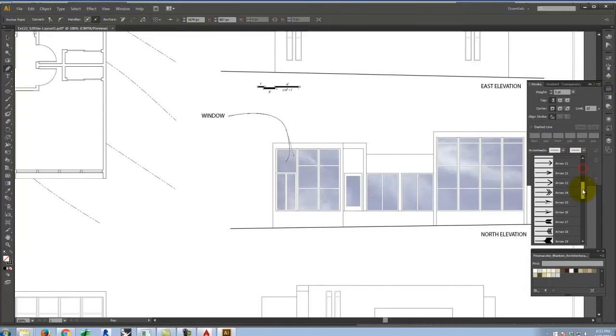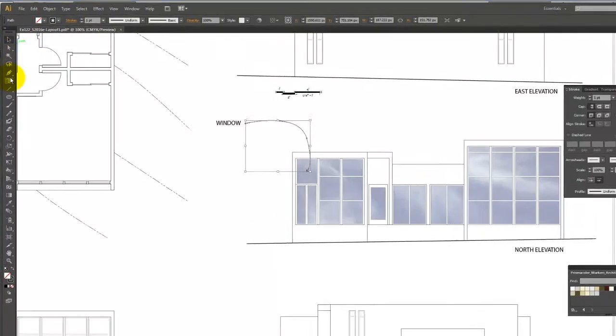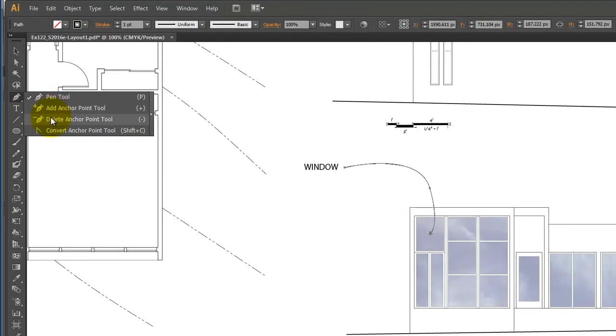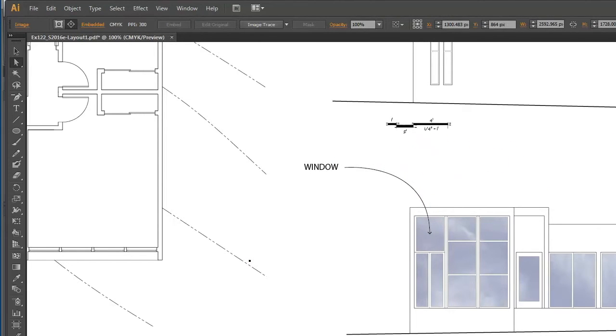I want to use that arrow, and now I have a line with that little point on it. Okay? If you don't like the curvature of it, a lot of times the easiest thing to do is to only have one control point like that, and then we can adjust this and say I want it to be curving, and do it as a nice simple sweep. Okay?